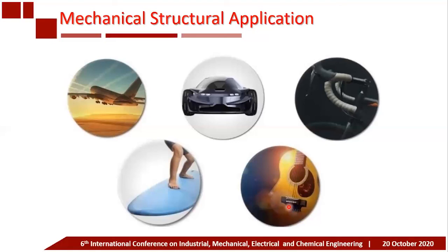Epoxy resins based on trishydroxyphenyl methane, for example, are among the important epoxy resins used in high performance applications. At elevated temperature, this resin shows excellent physical and electrical properties, moisture resistance, formulation stability, and reactivity and retention of properties.